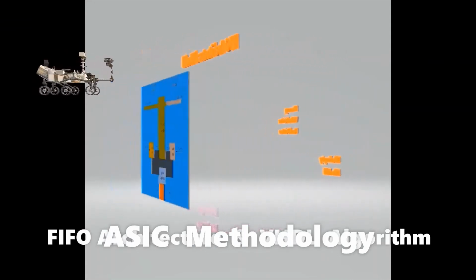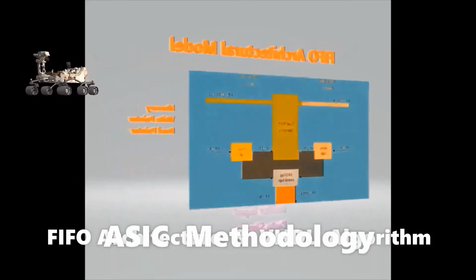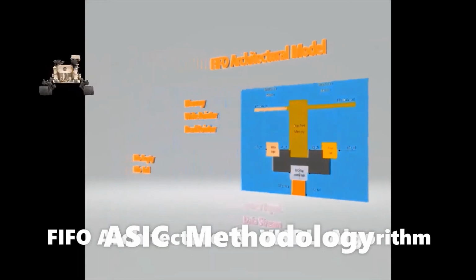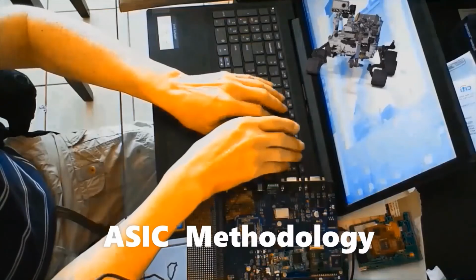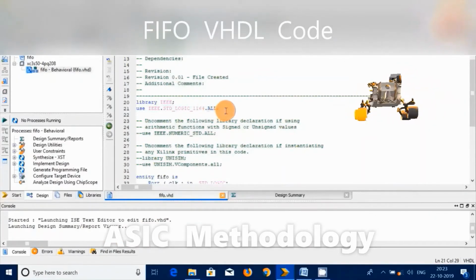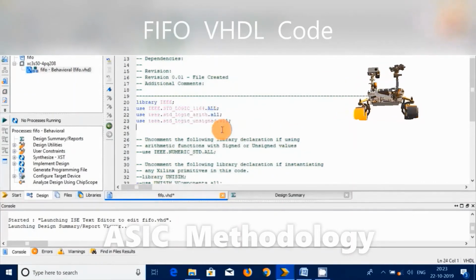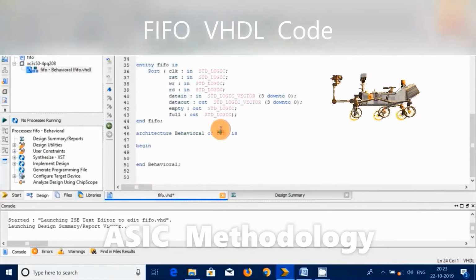The control logic drives the FIFO flags. FIFO empty flags that no data is present inside the FIFO RAM. FIFO full means no data can be written to the FIFO memory. And FIFO almost empty and almost full are also supported.